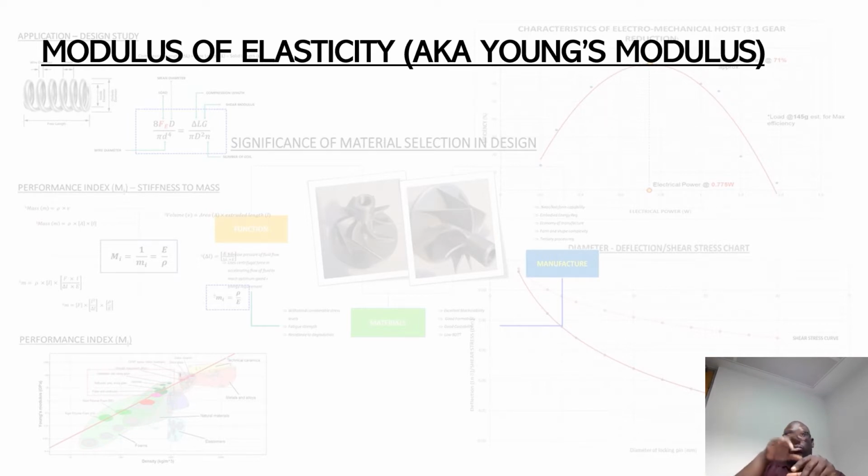Thus, when you plot the characteristic curve, the expectation for materials, other than elastomers, is that the material would exhibit a linear curve or a linear profile. The gradient of that curve is what characterizes the material's resiliency, thus the elastic modulus.